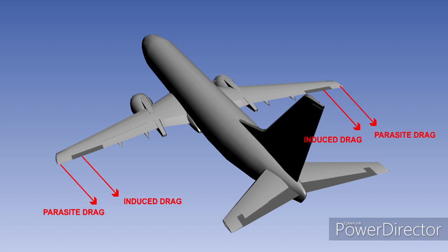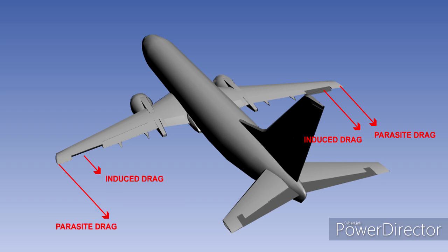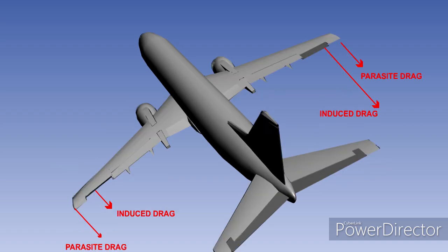With differential ailerons, the aileron linkage causes the upgoing aileron to move through a larger angle of deflection than the downgoing aileron. This increases the parasite drag on the upgoing aileron and reduces it on the downgoing aileron, thus reducing the difference in total drag between the two wings.